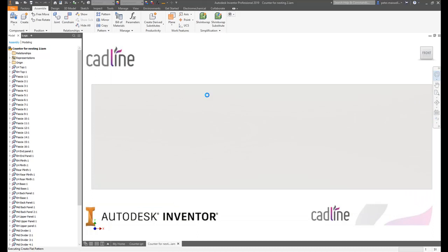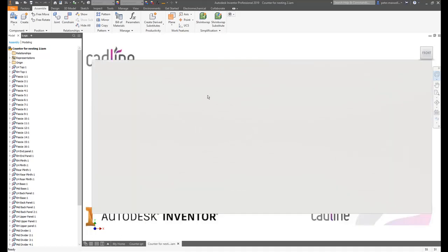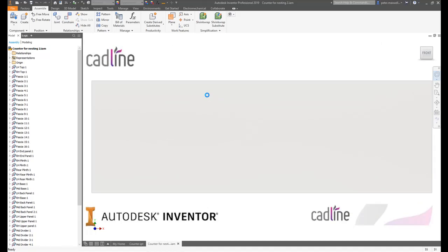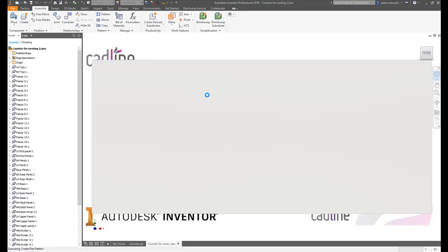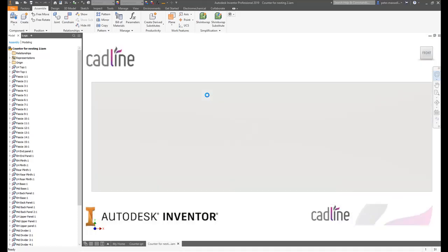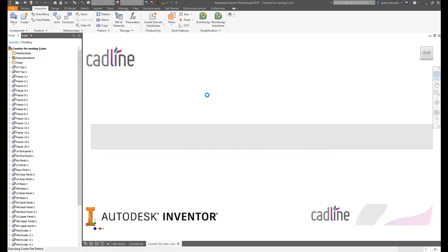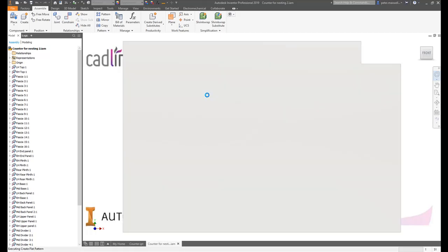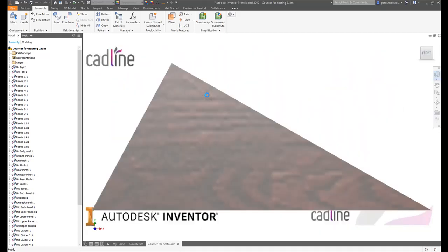And again, it'll take a little bit, but it's a lot quicker than you going and manually opening up each part and hitting create flat pattern. But the flat pattern is also useful because we can use it to get sort of cut lengths, the shape and size of it, so bring the flat pattern extents parameter across into our own individual parameter. Say if you wanted to minus 3 mil off all the edges for adding ABS edging or something like that, again we can use this method to do that as well.